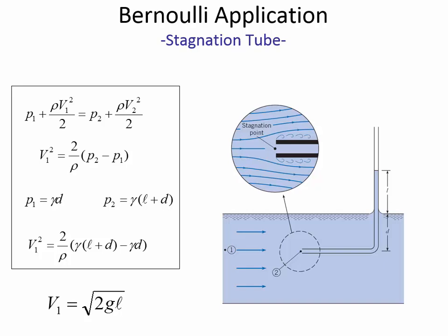And so it would be kind of an interesting experience to go through the process of designing something like this in the lab, measuring how tapering the edge of that tube gets you closer and closer to the actual velocity. Because you could measure the actual velocity of the river in other ways. You could throw a bottle and then watch the bottle pass a certain distance and use a stopwatch. And so you could find the velocity that way and then compare it to what this is predicting. Or there are these devices that look like a propeller on a stick, and you put the little propeller down and then it spins the propeller at a certain velocity and you can know the velocity that way.